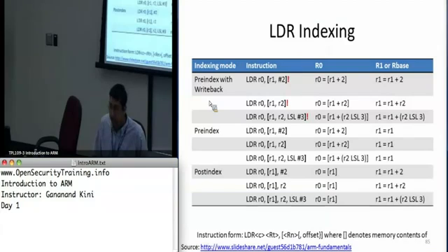Similarly, you can also include barrel shifts in your addressing operation. So you can calculate an address using the barrel shifter. Chances are it will be a nice even number, a power of 2. And you can update the register again this way. So you can do a lot of things in one instruction. Essentially, it gives you this sort of code optimization, code size.